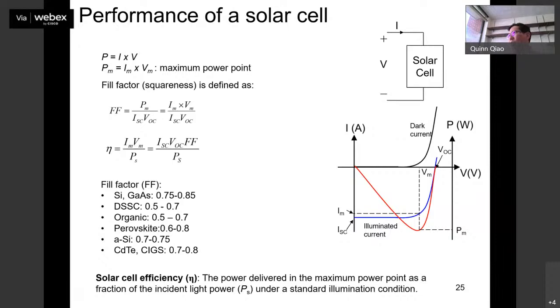It's different from silicon. With silicon, you make the wafers, and then you cut the wafers. That's easy. You make a good ingot and then you cut the wafers. That's it. It's fixed. With single crystalline silicon, everything is the same. But perovskite is a polycrystalline material, and under different temperatures, different solution concentrations, and different additives, the results are different. That produces too many factors for you to generalize or process, because a standard process is so difficult. That brings the challenge for commercialization and mass production. It's not easy to scale up. You can scale up easily, but how can you control the quality of the processing? That would be the challenge, and then how to scale up from lab-based small areas to big areas.